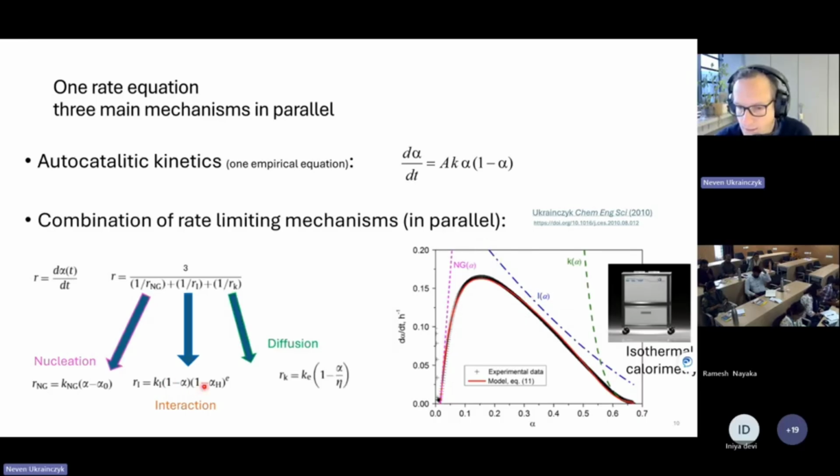This is the cement reacting with water. So I have the degree of reaction of cement and the degree of reaction of water. It's a bimolecular reaction, because you remember the reaction rate is K times the concentration, but now we have the concentration of cement and the concentration of water. So this is how a chemist would write the reaction rate if you have it in solution. But of course we have particles, so we also need to add the diffusion.